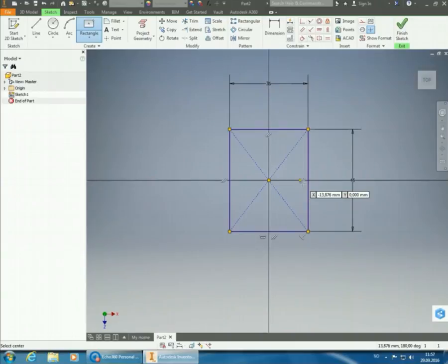And now we'll put another rectangle in, which is going to be the center hole. So attach it to the middle. And now it's a bit more difficult because now I have to look at what this hole is supposed to be. And it's supposed to be 11. And it's square. So it's 11 in both directions. 11 millimeters and 11 millimeters. Locked into place there. And press enter.